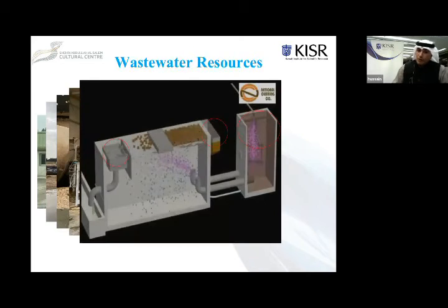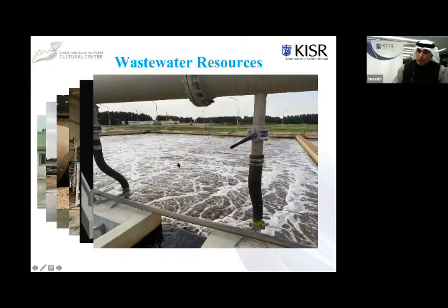And the secondary stage consists of 3 tanks, each consisting of 2 compartments. While the water gets inside those compartments, we add the coagulant and mix it with the water, and then it separates the scum and solid particles from the water, and we end up with the effluent at the left side of the tank. The last stage is the biological treatment, which is subjected directly to aeration, maybe for hours, before we send it out to the producer.